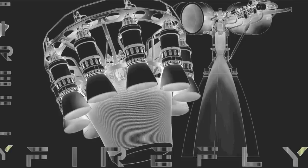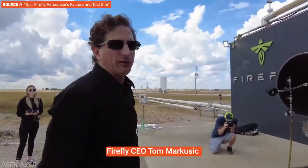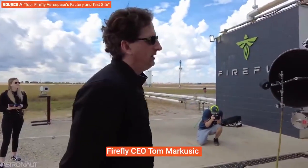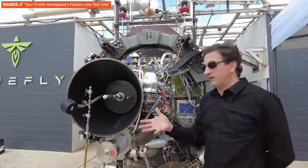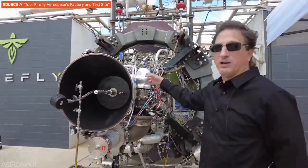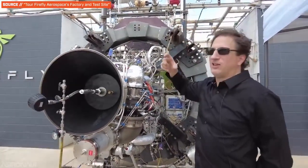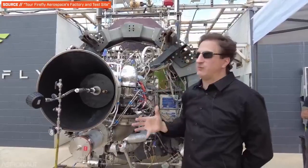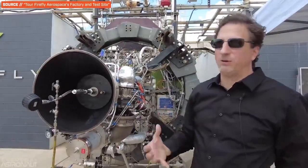That was Firefly. Their original Alpha design was going to utilize an aerospike engine to overcome some of the limitations of a pressure-fed system, and they thought that thing could make it to orbit. In Firefly Space Systems, we were developing a carbon fiber pressure-fed rocket. So on a pressure-fed rocket, to get that chamber pressure, you have to pay for it in the pressure of the tanks. Which means thicker tanks. Thicker tanks. So in the pressure-fed rocket, you're really trying to lower the pressure in the propellant tanks.